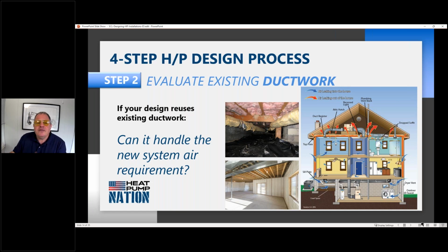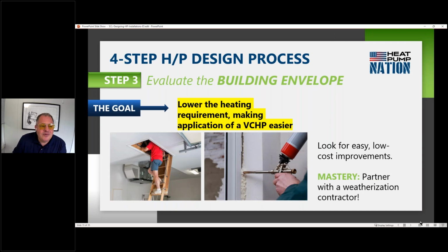And so first we do the load calc to understand how many BTUs. Then from that we can understand, okay, I need so many cubic feet of air per minute. We have to see if the ductwork can handle that without being noisy or just overly restrictive. And once you evaluate that, then you can start selecting the capability of that ductwork. You can then start selecting the equipment.